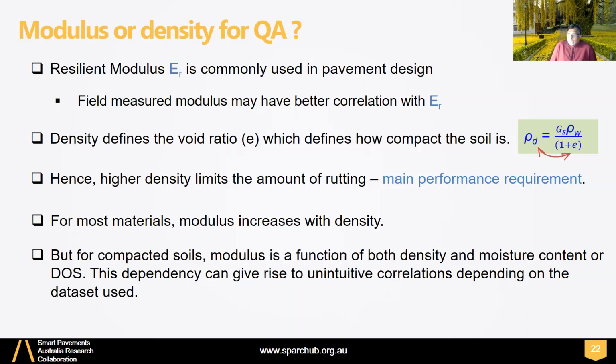Richard's equation is the moisture movement equation. Then we have a vapor flow equation based on diffusion. It is Fick's law. So Darcy's law encapsulated in Richard's equation for unsaturated soils, and the nonlinear Fick's law, encapsulated in the other equation for vapor, are combined together with the moisture storage coming from the water retention curve to simulate the variations when the rainfall is happening, and the evaporation is happening when the rainfall is not there, and the runoff is happening during rainfall.